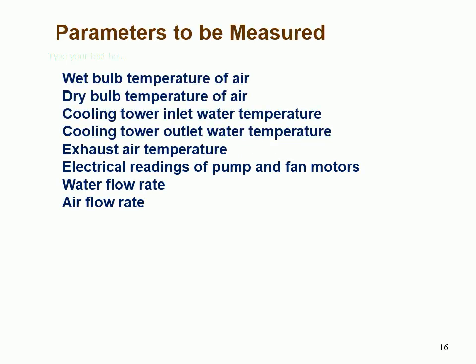In the next section you will learn how to assess the performance of a cooling tower. The performance of cooling towers is evaluated to assess present levels of approach and range against their design values, identify areas of energy wastage and to suggest improvements.